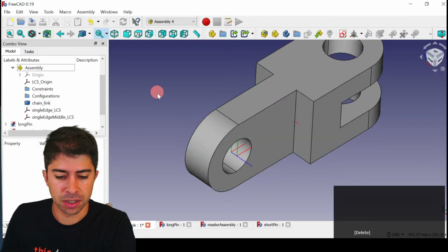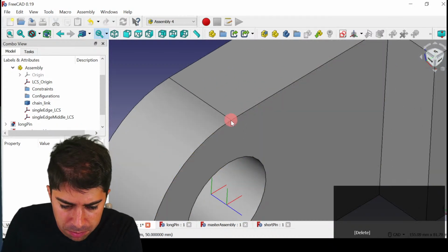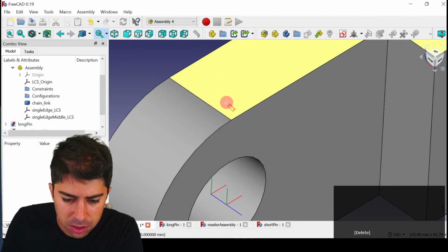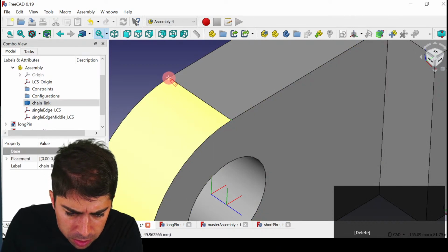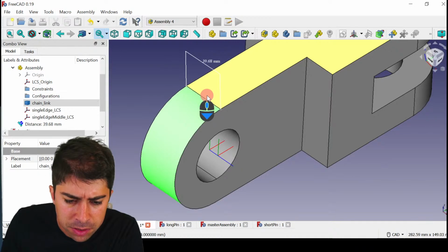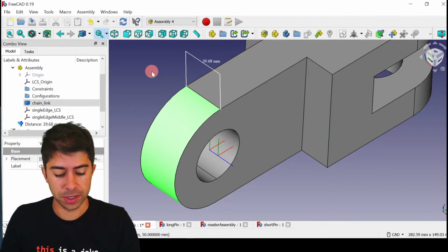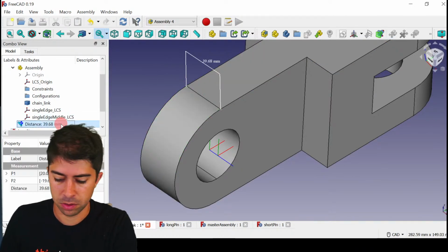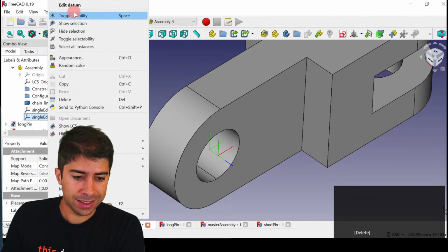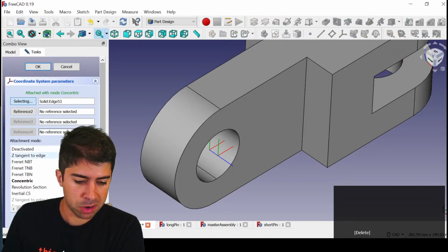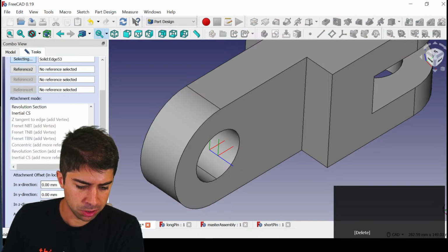With this measurement stuff, you do miss the measure tool of SolidWorks. Let's see if we can get a point there, point over there. Okay, that is about 40. All right, so the middle was 20, so I got that one wrong. Okay, so we need to change the middle one. We edit that and we offset it not by 10, but by 20.